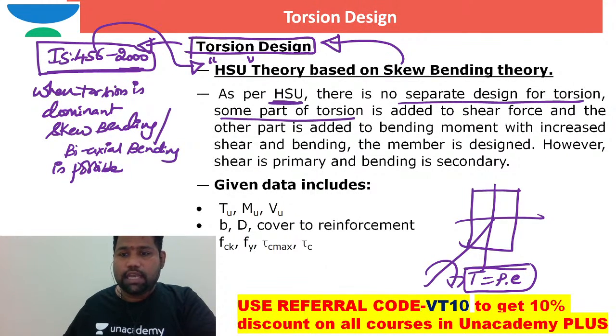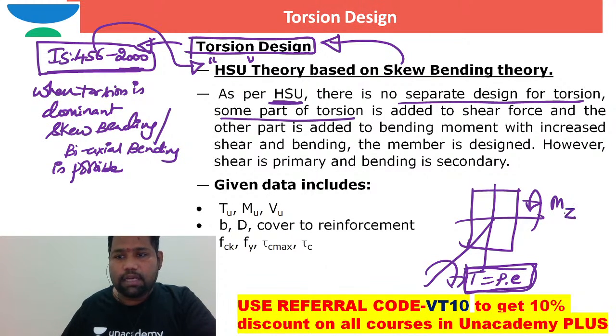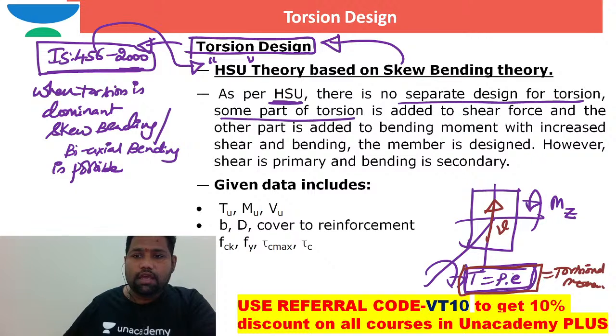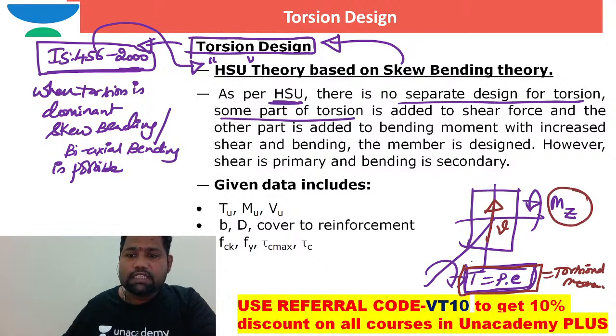So if the torsion is there, in order to resist it, already about the x-axis there is some bending moment, maybe Mz, and there is a shear force, which we call V. In order to design for this torsional moment, T is equal to P into E, some part of this torsion has got added to the bending moment. Some part of this torsion has got added to the shear force.